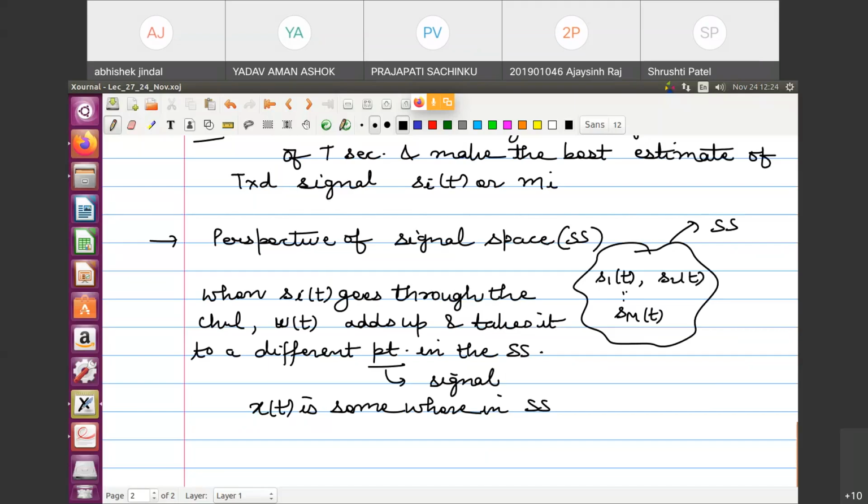That is why the whole structure will be probabilistic; it cannot be deterministic. It means that in what we studied as error rate due to noise, if you are sending 1, occasionally it might happen that the received values are less than lambda, so that you decide in favor of 0. So the average probability of error: a decision rule is fixed but it cannot take decisions deterministically. It means there can be some error; sometimes it may decide correctly, sometimes it may take a faulty decision. So that is the whole perspective.